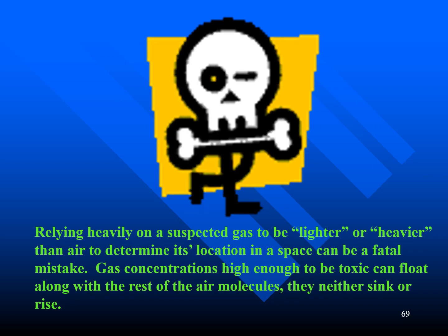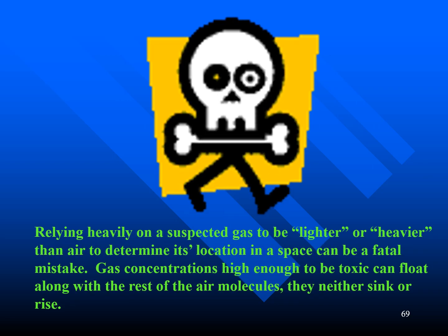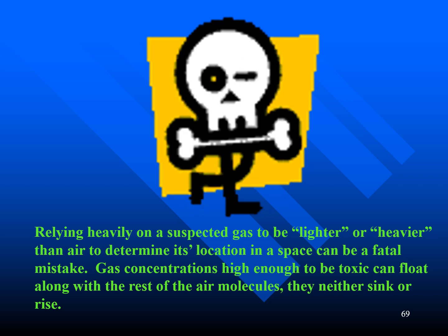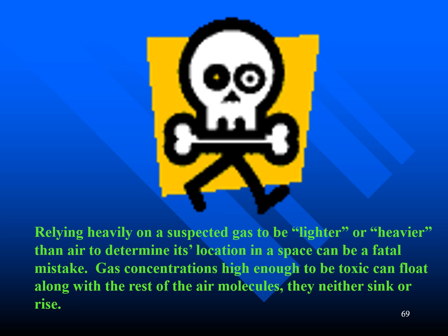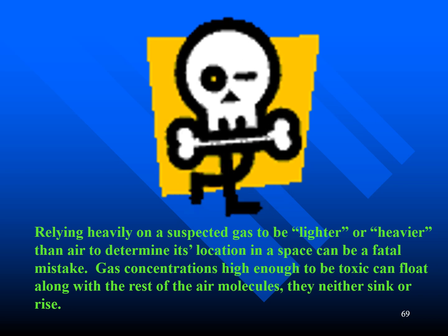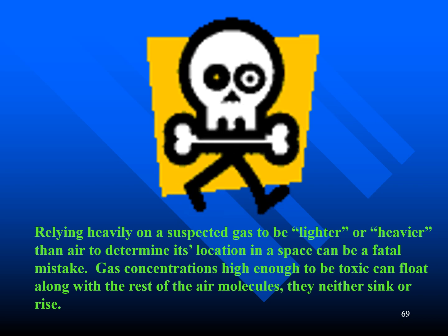Here's a word of caution. Relying heavily on a suspected gas to be lighter or heavier than air to determine its location in a space can be a fatal mistake. Gas concentrations high enough to be toxic can float along with the rest of the air molecules. They neither sink nor rise.